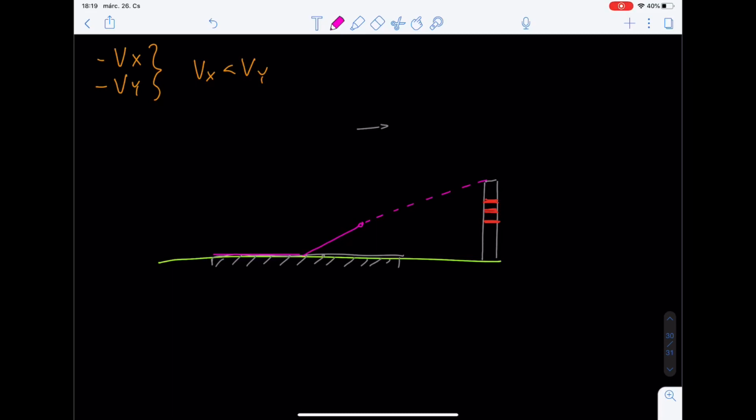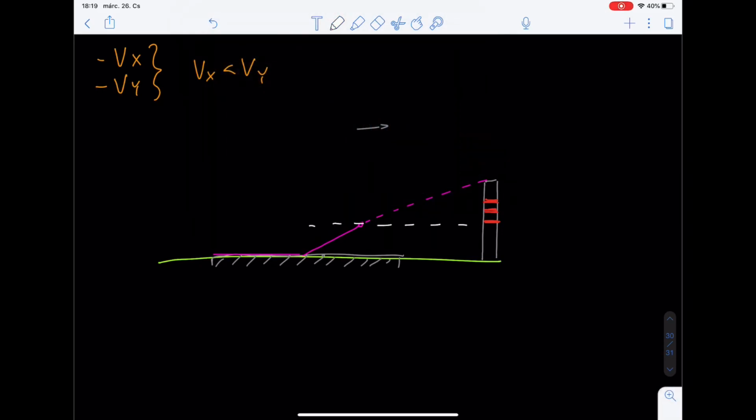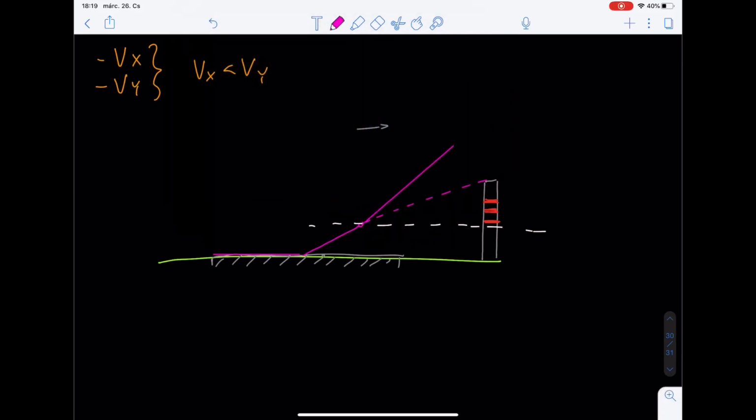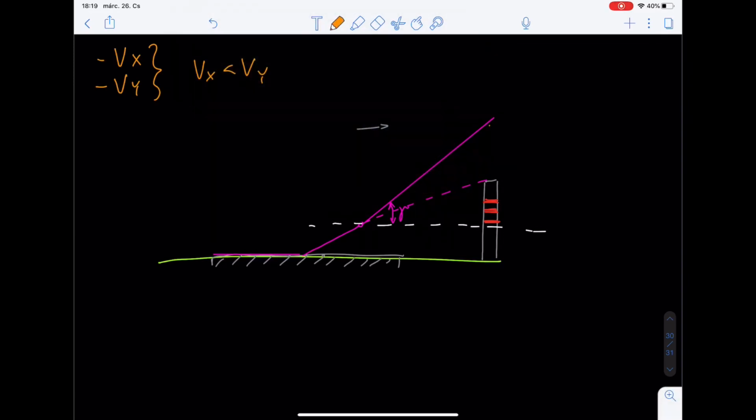So the right answer in this scenario, of course, is you want the best angle of climb, right? Because best angle means that this gamma angle is going to be the highest, and what that achieves vertically over the obstacle, from the highest point of the obstacle, is that I'm going to have a nice large separation, a nice large distance, right?